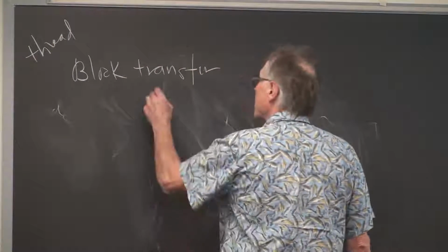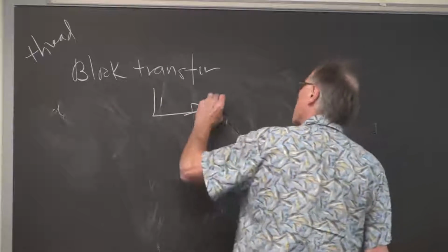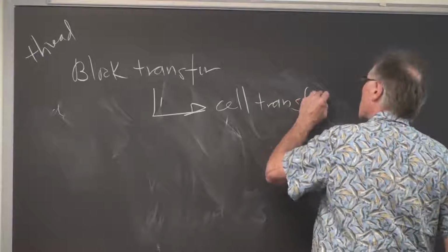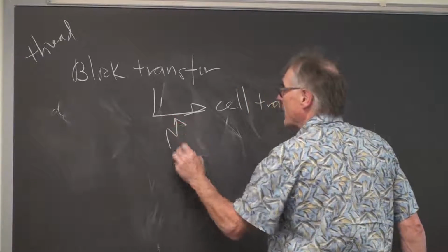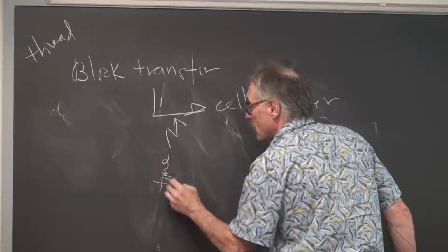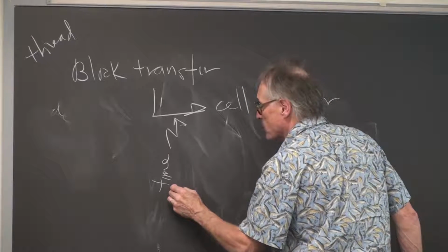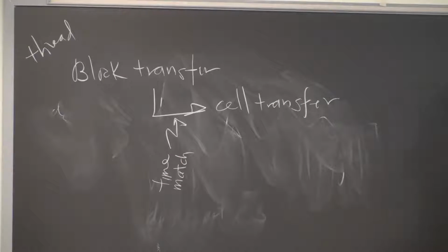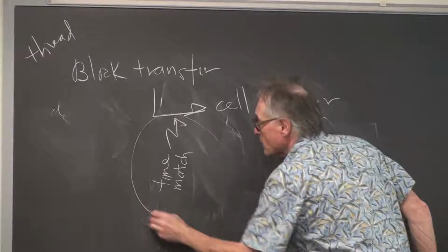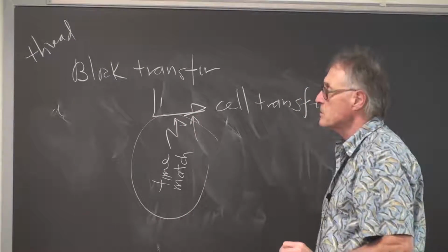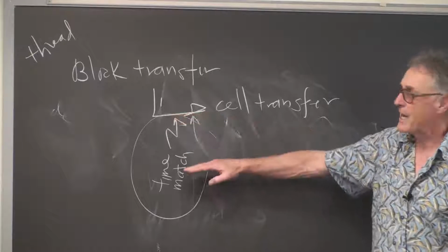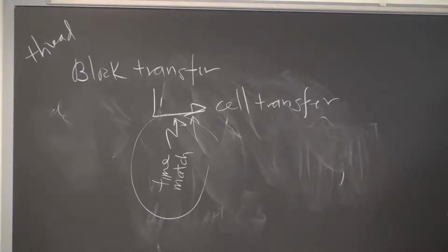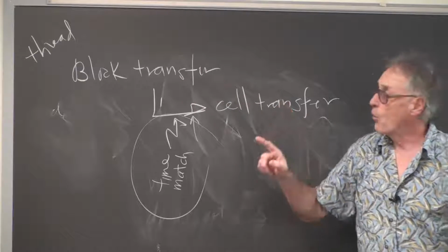And then each cell transfer making up that block transfer will be triggered by a timeout, by a timer match. This is a hardware connection. So there's no software involved in this timer match cell transfer. Therefore, you get good CPU efficiency for the cost of setting up the block transfer once per sound.